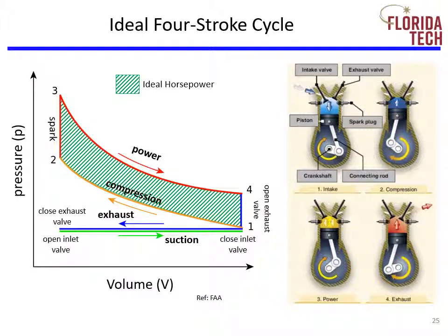Typically, for every fuel molecule, there are 15 air molecules. The mixture adjusts the amount of fuel necessary to maintain this ratio. The throttle, on the other hand, controls how much of that ratio is let into the cylinders. The more the throttle is open, the more fuel and air enters the cylinders, and therefore the more power the combustion will produce, making the engine run faster.